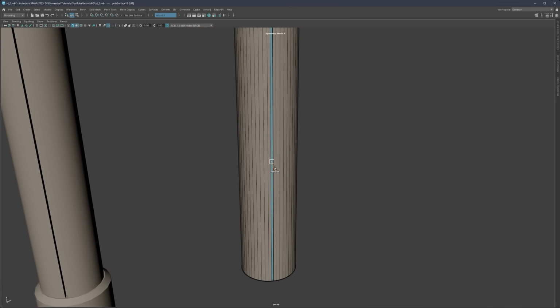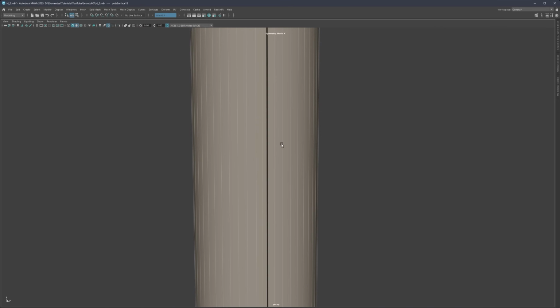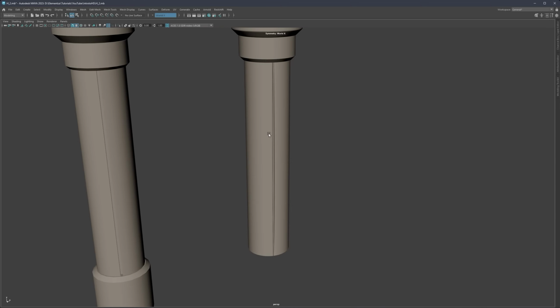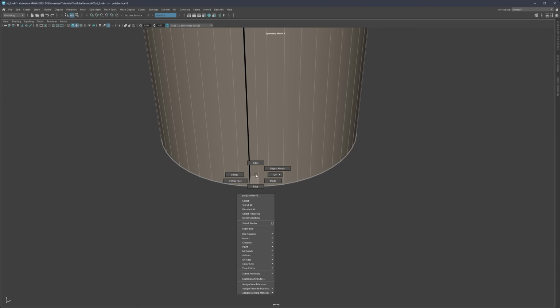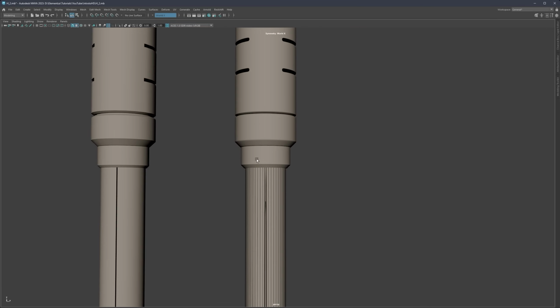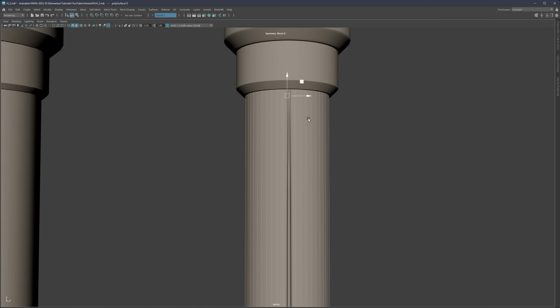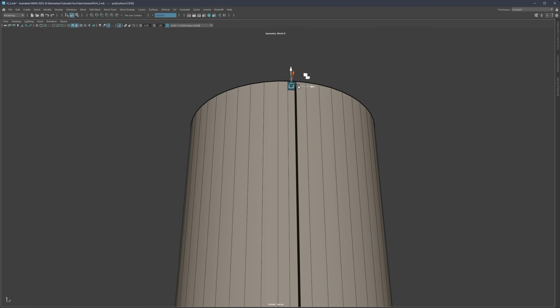Depending on what we get, I think this might be fine. So just pushing it on the inside and no support loop necessary because I'm pretty satisfied with how the highlight looks. The only thing we want to delete is this face from the bottom and the same face from the top. So again, go to object mode, Control 1 to isolate, and delete this face.